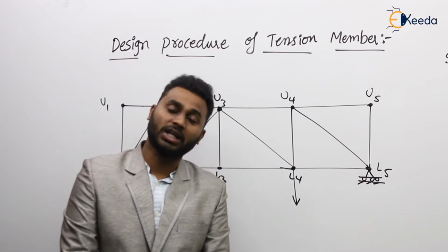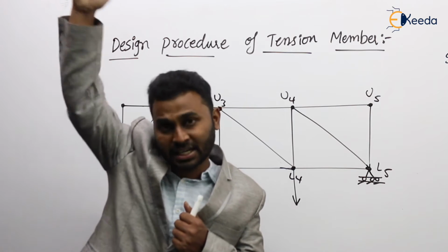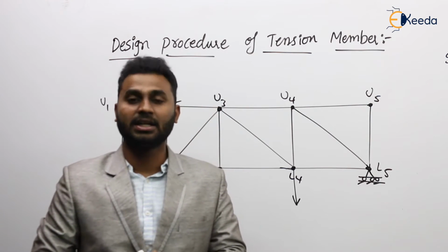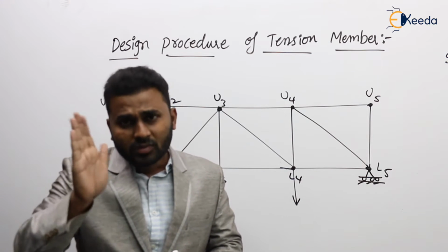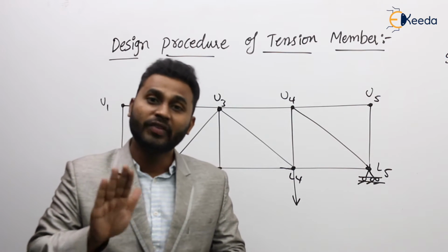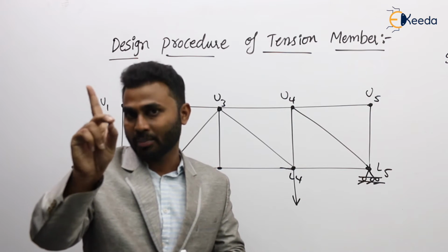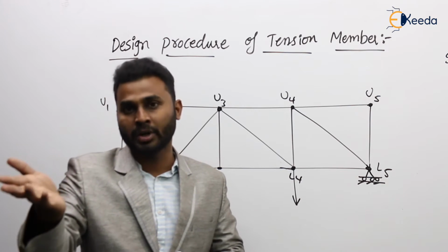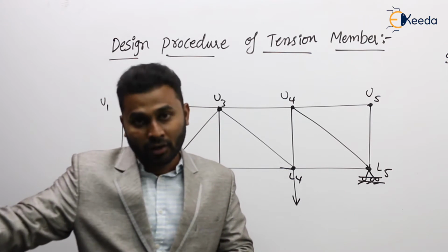Now if we take a roof truss, it is provided at some altitude, at some height. At that height, obviously wind loads are predominant. So based on this, a roof truss is subjected to wind load also. There, in comparison to the live load, wind load is predominant. So now a roof truss is mainly subjected to dead load and wind load.